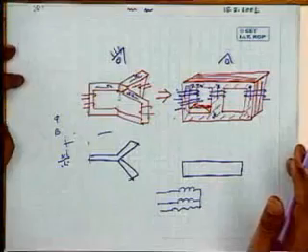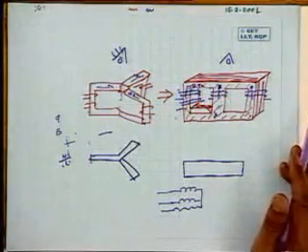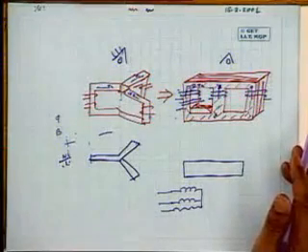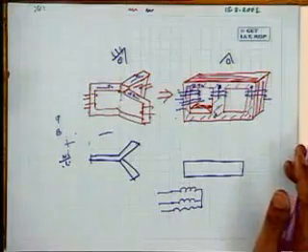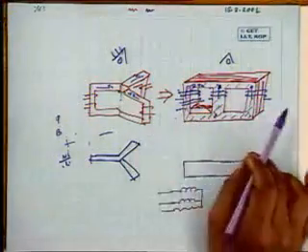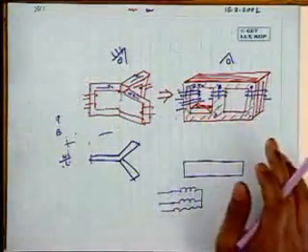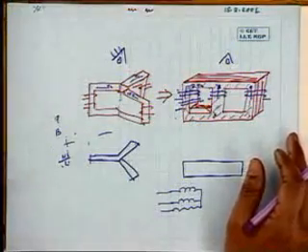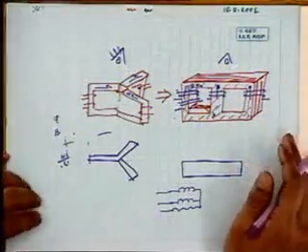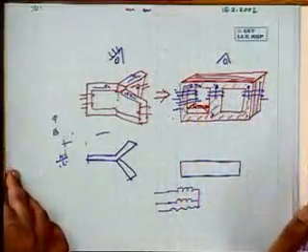And as I have pointed out already, given a transformer rating, magnetizing current is of the order of 2 to 5%, 2 to 3%, magnetizing current alone, not no load current. It will be about 2%, 3%. And they are different. At that level of current, there may be slight unbalance in them. That we sacrifice. No load current we sacrifice. However, you will get a 3-phase transformer like this.